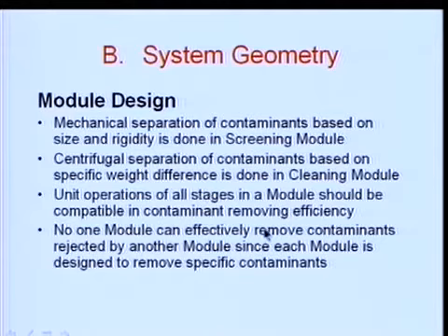So, the same thing follows with washing, thickening, flotation and the modules. And no one module can effectively remove contaminants rejected by another module, since each module is designed to remove a specific contamination. So, if screens are there, let us say medium slots of screens, and you are working with 2 to 3 millimeter slots, and then you follow them by cleaners, that is fine. Now, what is removed in the screens is okay, but what is removed in the cleaners, if you take it back in the system, you are going to have problems.